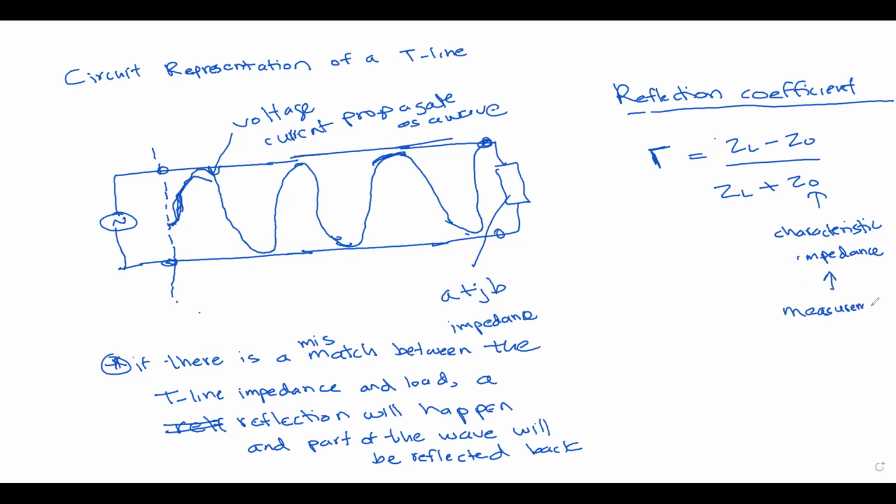You need to do a test to find the characteristic impedance of the line. Normally, for transmission line calculations, we take the value of 50 ohms as the characteristic impedance. This is not applicable to all transmission lines.